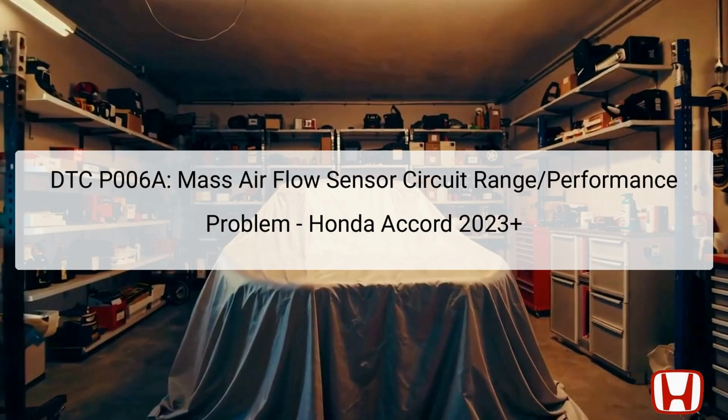The MAF sensor is crucial for delivering precise air intake measurements to the PCM, which optimizes fuel injection and ignition timing, playing a significant role in engine performance and emissions. If your Accord's engine exhibits rough idling, stalling, or reduced power, it likely relates to issues detected by this code. It's essential to troubleshoot this DTC effectively to avoid further complications or engine damage.